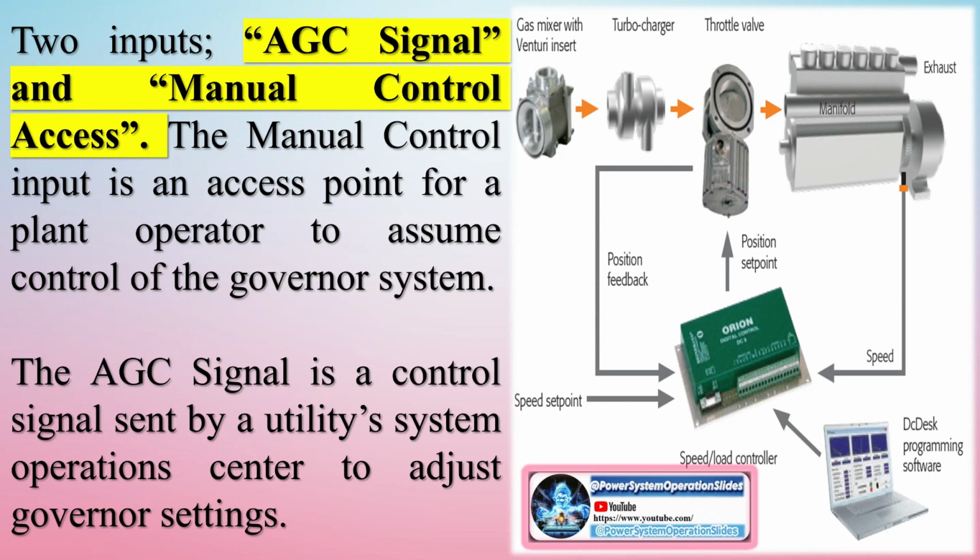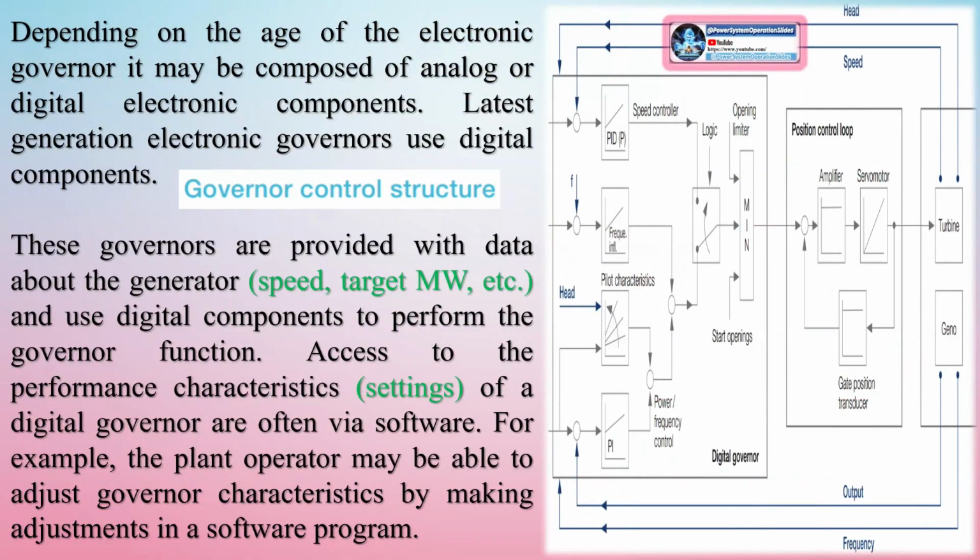Droop and load sharing. Droop is a fundamental feature of governors that allows multiple engines or generators to share a load proportionally. In simple terms, droop refers to the reduction in engine speed as the load increases. This intentional reduction helps stabilize power generation in systems where multiple generators are operating in parallel. Without droop, engines would compete for load, causing instability.